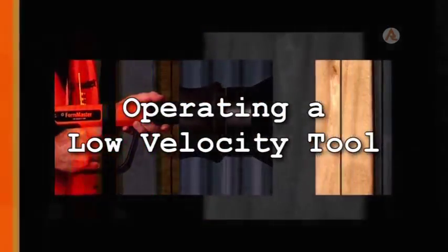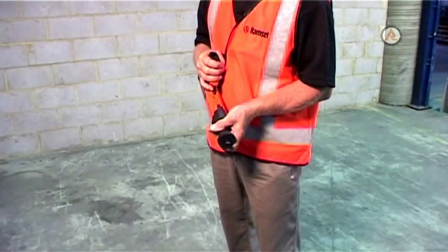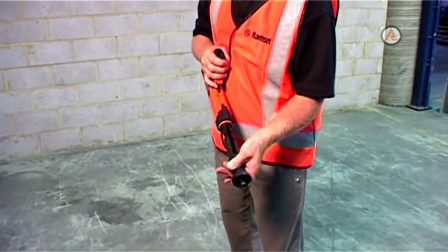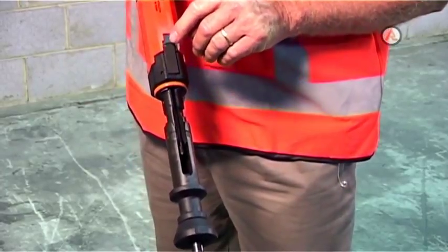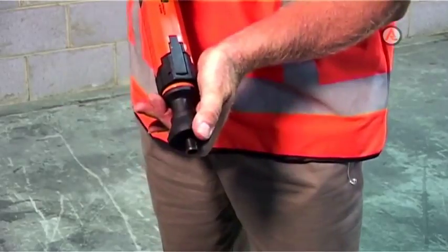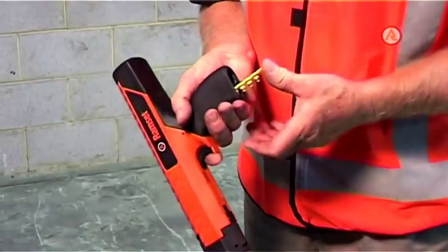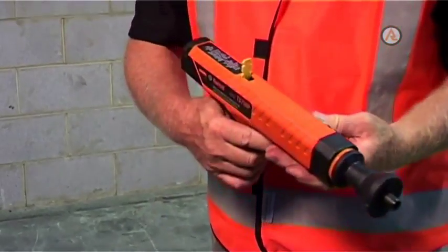Operating a low-velocity tool. To cycle the tool shown, hold the front barrel by the rubber grip provided. Slide the barrel assembly forward firmly until it reaches the barrel stop. The piston is returned within the barrel during this forward movement. To close the tool, the barrel assembly is pushed back until the closed position is reached. With the tool in the closed position, the power load strip can now be inserted in the hole provided in the base of the rubber handle.